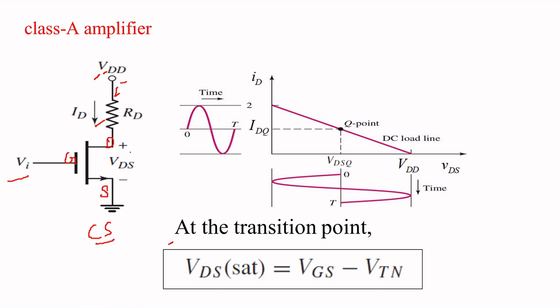So the DC quiescent point will be generated and fixed. Only then will you be superimposing your AC signal in your circuit, right? Here you can see the ID versus VDS. This is your quiescent point, which you fix when you consider VA is 0, that is your VDSQ and IDQ. There is a corresponding design formula for VDSQ and IDQ also, that we will see in the coming slides.